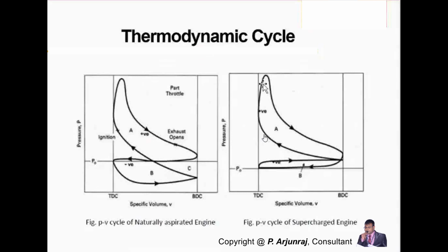So again we have the increase in pressure because of the supercharger, where we have a higher increase with respect to the intake stroke, and correspondingly a higher pressure increase with respect to the second stroke, the compression stroke. Obviously this higher increase in pressure helps the expansion during the power stroke, so that the pressure is higher than the pressure you would get using the naturally aspirated engine.